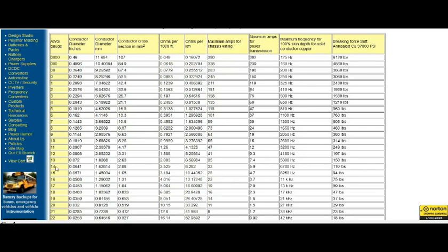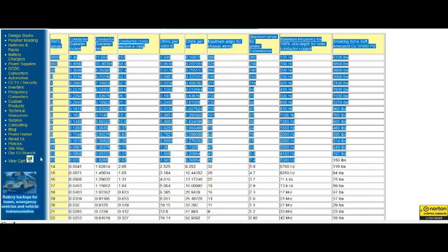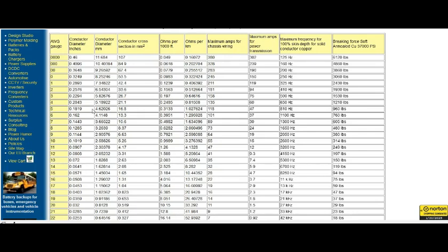And you can see if you start to go with thick wire, I mean, here you're at 5 kilohertz at 13 gauge, or 7 kilohertz at 14 gauge. If you go down to like 8 gauge, you're at 1.65 kilohertz. So it starts to slow down a lot before you see skin effect begin to become an issue.